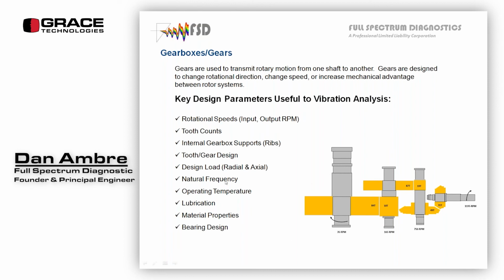We want to know what the loads are in the gearbox. If you have varying loads all the time, you're not going to have very good trends. I did a job in a plastic extrusion. They used to make garbage bags, and they had 6 different settings, 6 different products that they were putting out. They all had different loads. They all had different speeds through the gearbox, different extrusion process, basically on the same gearbox. We'd go in there monthly, we'd take data, and the trend was all over the place because they were constantly changing what product they were producing, and we never bothered to take a look and see what that effect was.